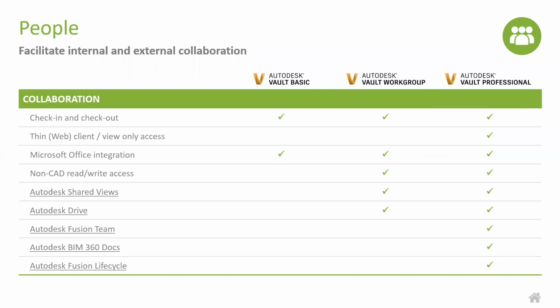All right, we got a question from Gage. What type of attributes can you pull from the associated and linked files? Can you do custom ones? Certainly you can. There are a lot of properties that these Word documents and Excel documents hold, and you can have those come into the files. You can map certain properties from those files into properties within the vault, much like you can with any regular old CAD file. So I urge you to try for yourself: if you know how to do property mapping for CAD files, go ahead and do the same thing for Office documents and see what happens.